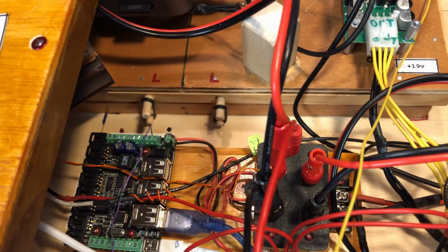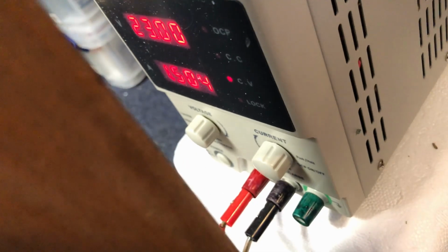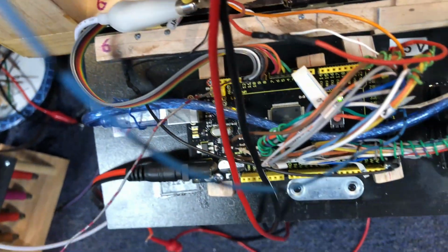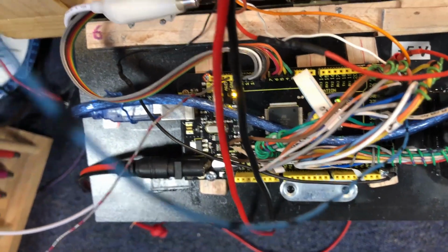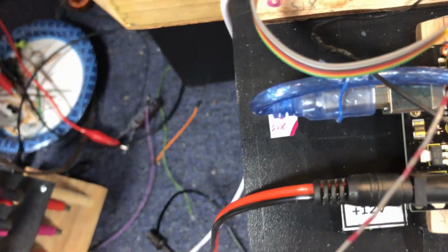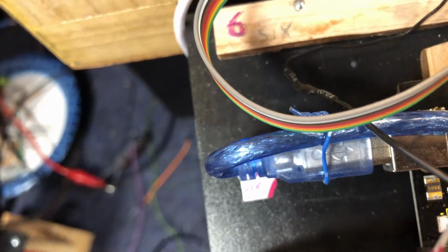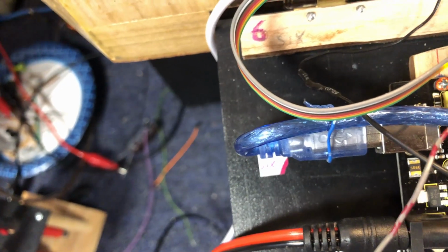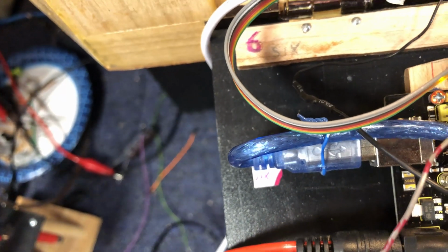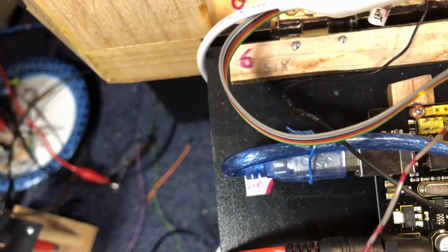DC power from a power supply like that one, and it will set the voltage up. And what I had to do on this Arduino, besides write a little program, is it was being powered by the USB cable off of the PC, but the problem with that is the PC wasn't powering up, so this board wasn't powering up, so I couldn't use it to turn the PC on.